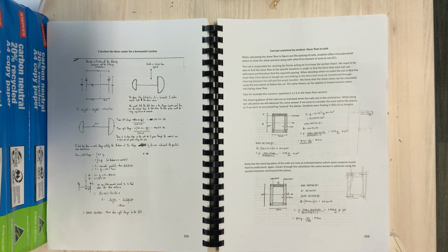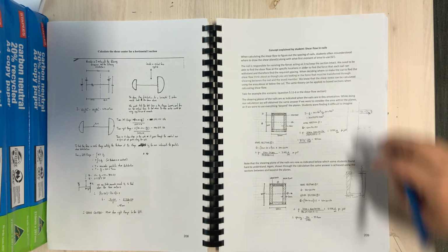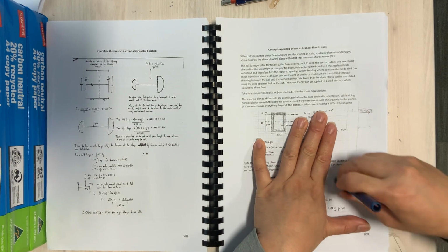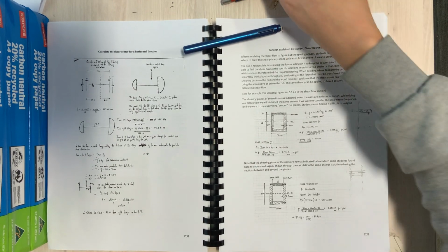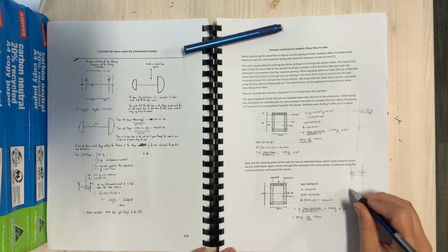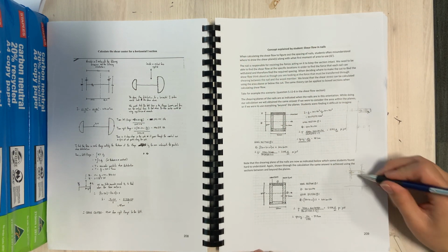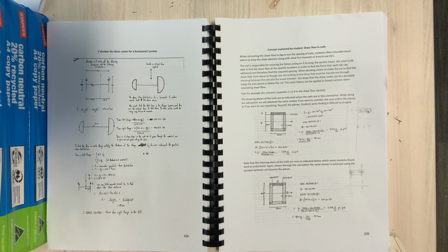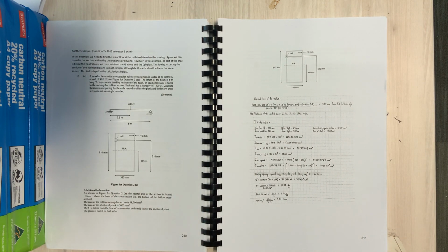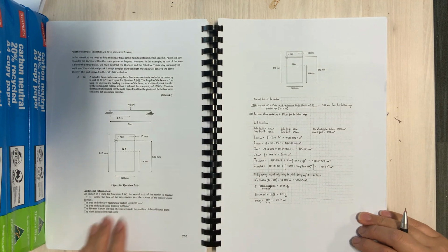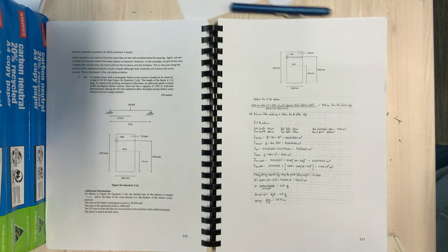So it's almost the same calculation, but you'll be working off that instead. And then obviously divide by 2 because you've got 2 shearing planes, so I can see the 2 there, or you can just take half. Okay. And then from there you'll be able to work out the spacing. So that leads on to question 2A from the 2015 exam.